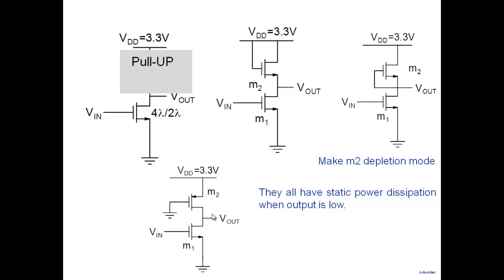Because the load element that you see here, you are not switching it on or off. Pull up is a constant, whether it's connected to VDD or VGS is permanently 0 or whatever resistor or connected here. Okay. By the way, this particular method of making an inverter, we'll see later on, has certain advantages. It's called pseudo NMOS.